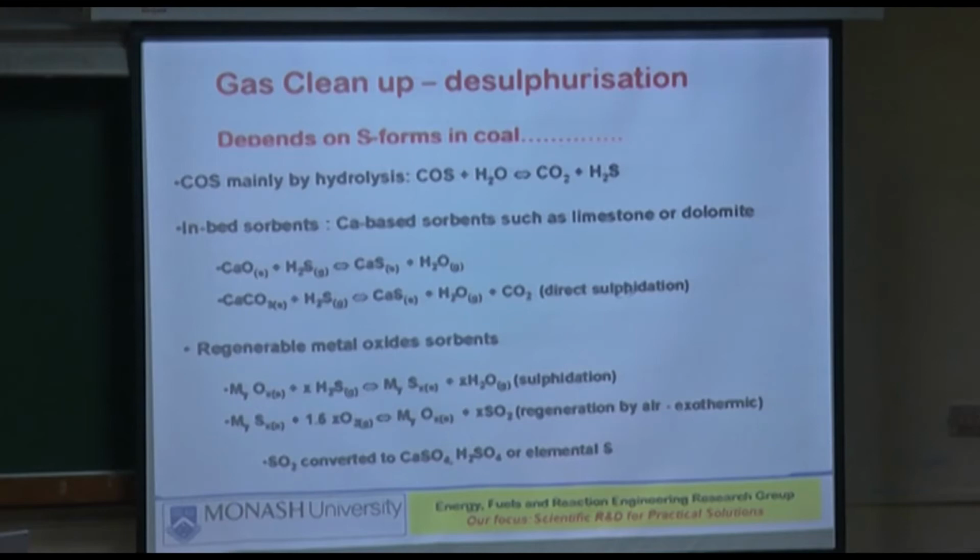If you are involved in fluidized bed gasification, then fluidized beds provide the right temperature for in-bed sulfur capture, so that you can capture the majority of the sulfur in the bed, because fluidized beds operate around the ideal temperature for limestone-based, calcium-based sulfur capture, at around 850 or so.